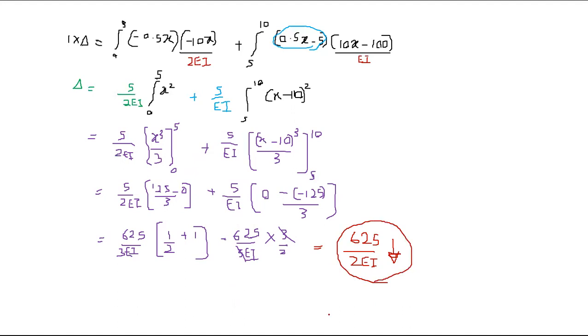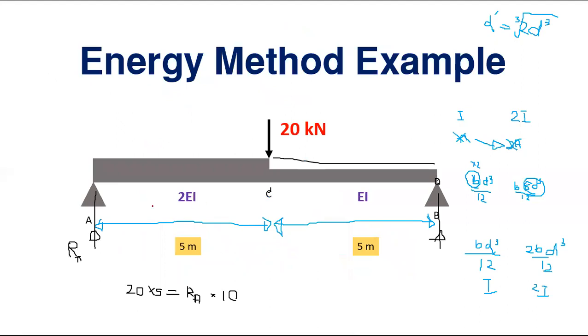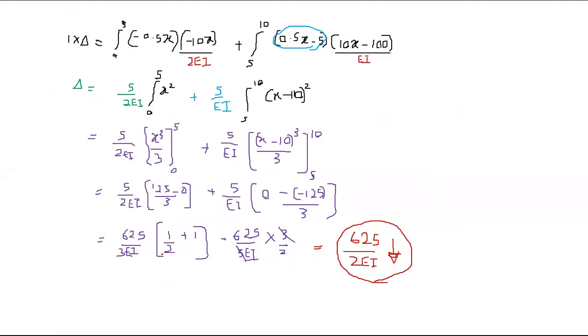And you can, in the same way, check for the end slopes. So I will check one of the end slopes, right? Let's say I need this theta. So that also it's possible to obtain from the energy method. So what you need to do is, your linear displacements are correlated with linear force.